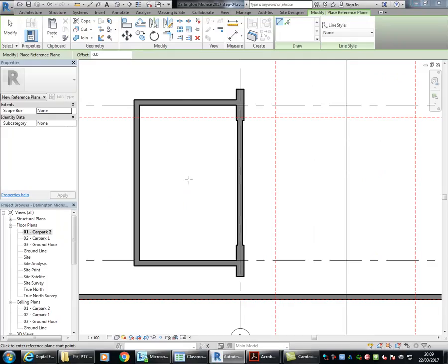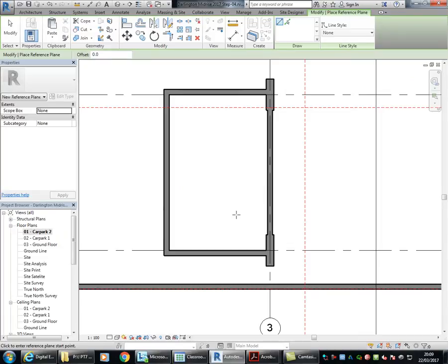So, okay, how wide does a fire stair need to be? That's one of the things in section D. You read through that. It tells you the width, and it should be 1 metre clear between your handrails. That's the minimum width for required access. So that's a good figure to remember. Then, depending on the number of people in the occupancy, it could be higher. But 1 metre is the minimum.